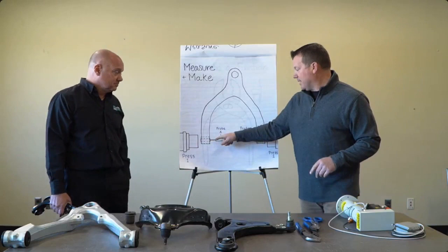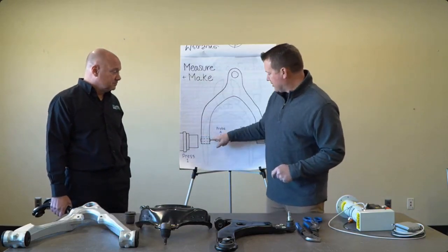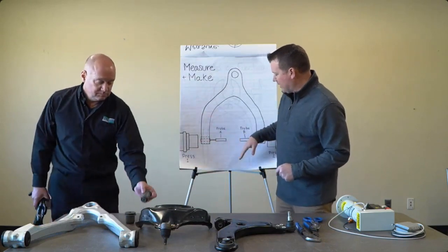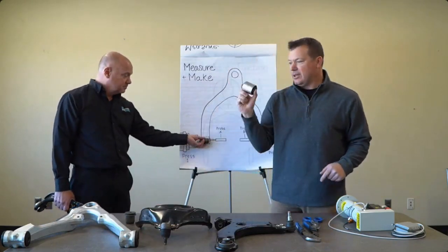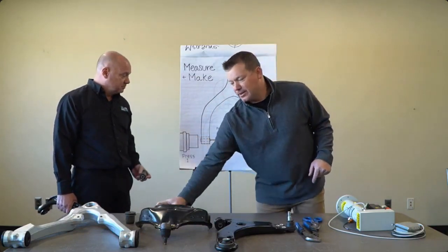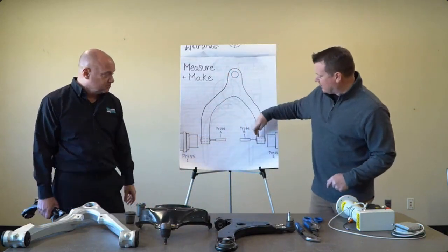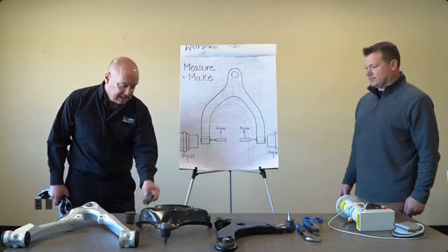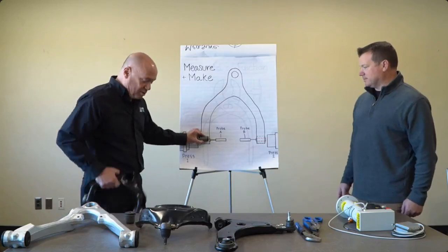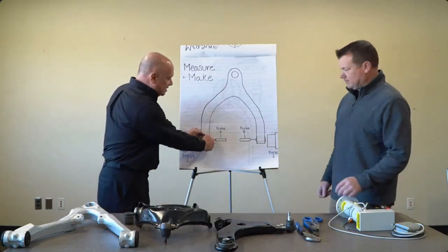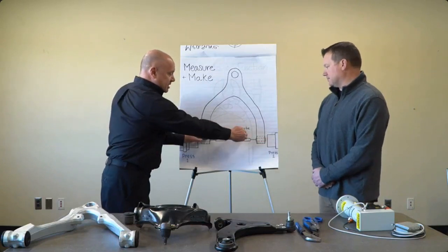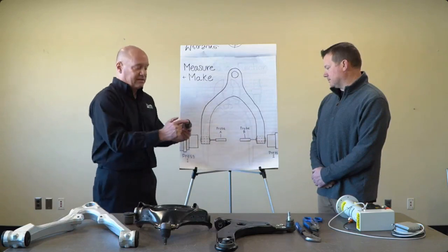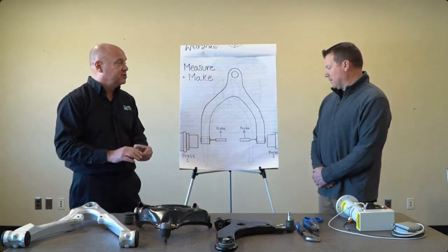So we can then take out the deflection, measure the point Glenn referenced there. So deflection's gone, force is gone out of that equation. Variations in this bushing are now taken into consideration, and these parts get pressed consistently from one to the other. So now when you're pressing these bushings in with the presses, you press until the probe says that this dimension is correct. You're not pressing the can to a position, but you're pressing the critical surface to the position.